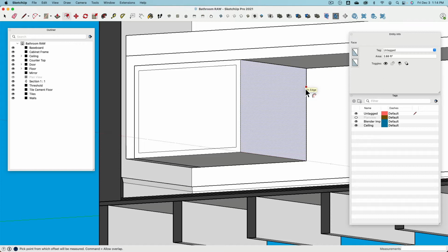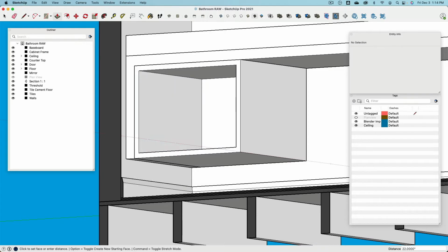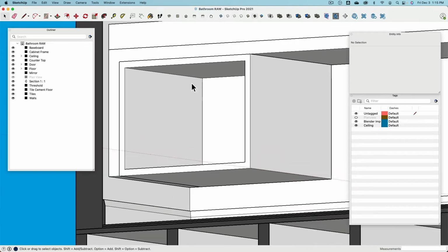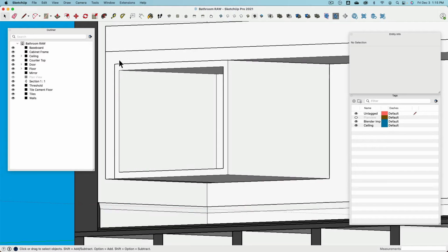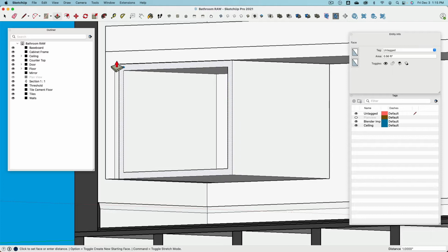When we have here 1 inch material thickness to the back, now it's a question, do I want to have half of an inch back? Because I don't really need a strong one to the back. Let's say 1 inch too. When this is 23, then this face I only can move back 22 because I want to have 1 inch of a material back. My door should sit right in front on it, but flush with the surface. So this actually needs to go back 1 inch. There. Then triple click, group.